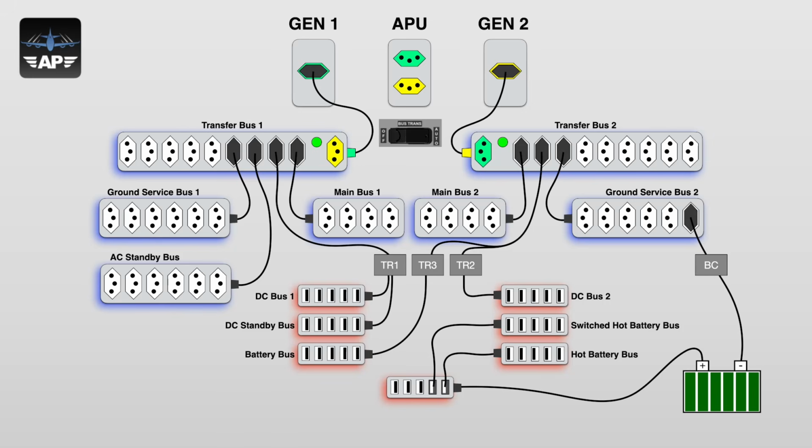They are all reserved to be used in case of the energy supply malfunction of the generators. You see, I think that the beauty of an electrical system is designing it in a way that it is able to keep feeding energy to the essential equipment no matter what. And this system is doing just that. All the essential equipment of the Boeing 737 is connected to 5 different buses. The 5 buses are all of those that have the name battery or standby on it.